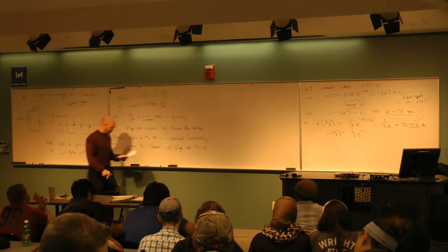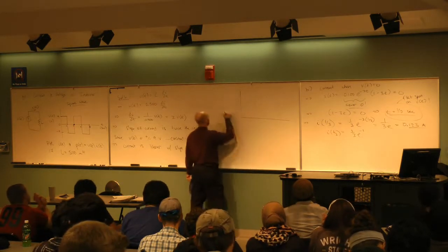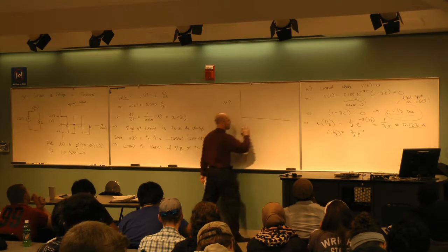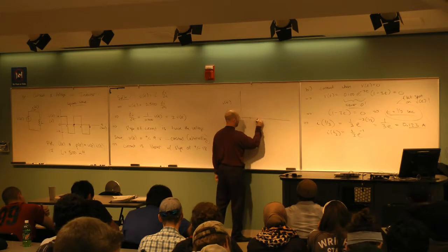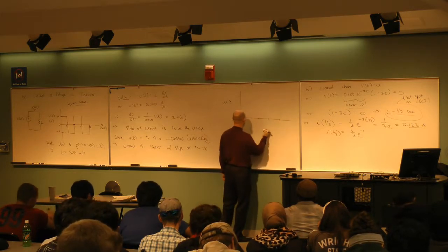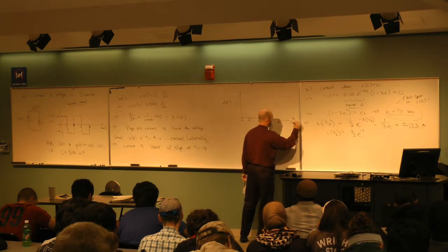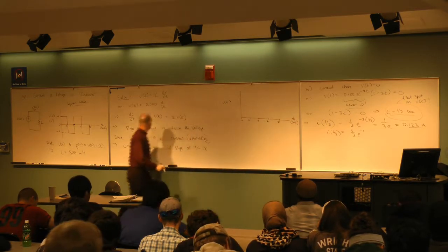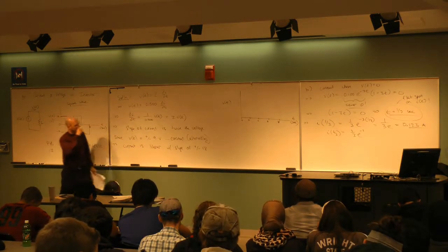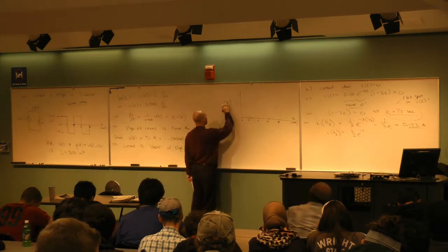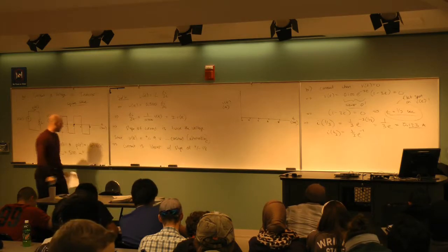Right? And then when I get back to this point, it's the same argument again. All right, so how do I get these words onto paper in terms of what this plot would look like? So I'm going to have I of t. I've got to have tick marks on the x that look the same as the original. So 2, 4, 6, and 8. Okay, and this is t over here in seconds. And I of t, if I put everything in base units, I got volts over here, then I of t would have units of what? Yeah, amps. Okay, and so we ought to be able to start drawing this.